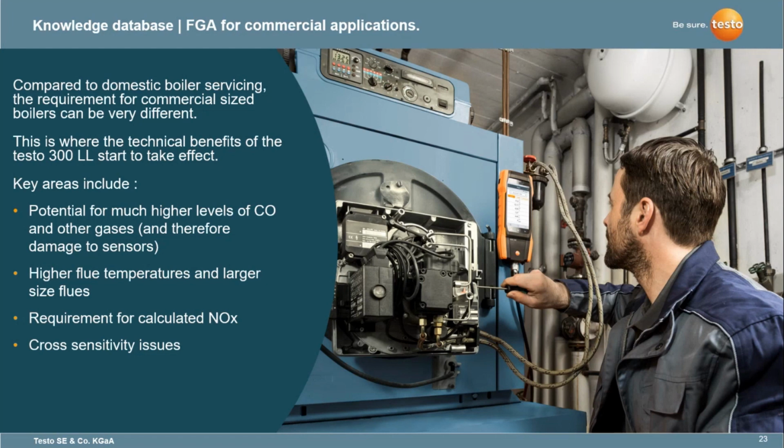And typically, it's an ongoing issue in the UK. We have people who are using the wrong analyzer for the wrong job. We've got FM companies, for example, trying to use domestic analyzers on very large commercial boilers, and then wondering why they've got very high service bills because their engineers are always just knocking CO sensors out through spikes. Sometimes it's about picking the right analyzer for the job.